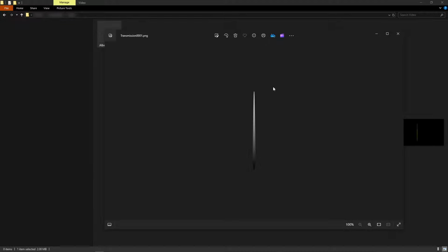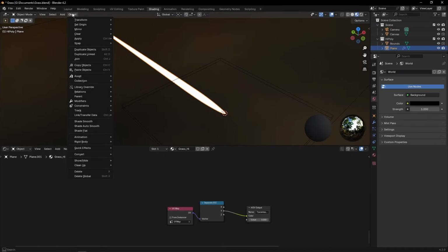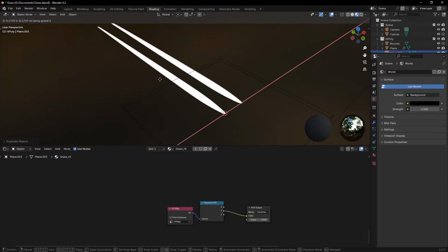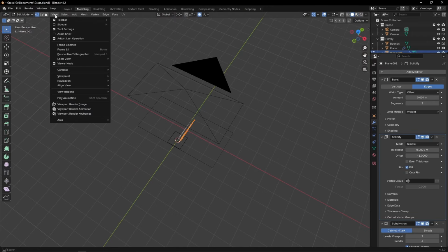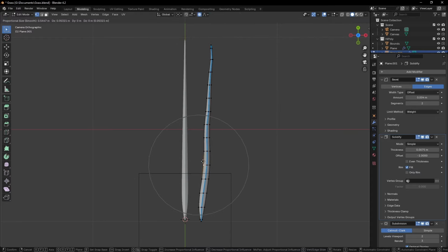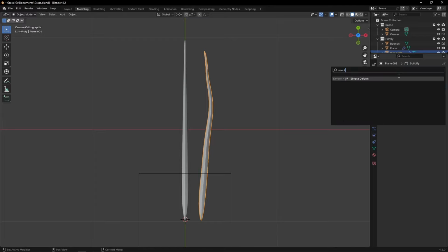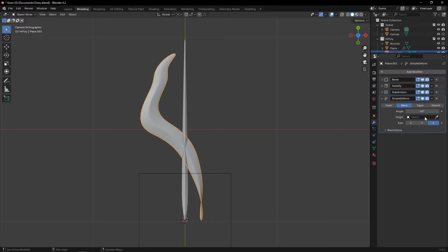Rendering a single grass blade is quite dull though, so let's create a couple of grass clumps. I'll fast forward a bit here, because in the end it's just a matter of duplicating that one grass blade, entering edit mode, and using proportional editing to move vertices around and create interesting shapes and whatnot. You may fool around with modifiers as well, like bend, twist, and so on. The sky's the limit, let your creativity speak.